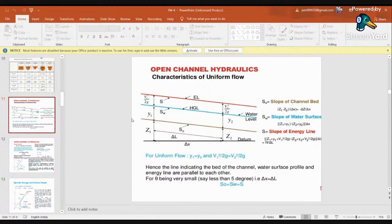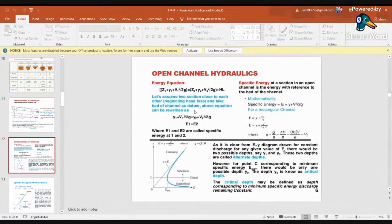energy at this section. Okay, so for the left hand side my energy will be z1 plus y1 plus v1 square by 2g, and for the right hand side my energy will be z2 plus y2 plus v2 square by 2g plus HL, that is the head losses. So these two energies must be equal for satisfying the energy equation in that section.